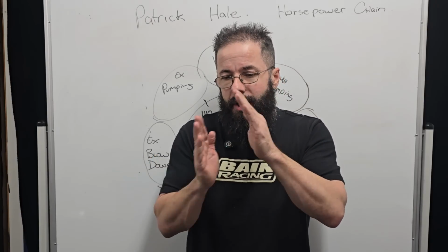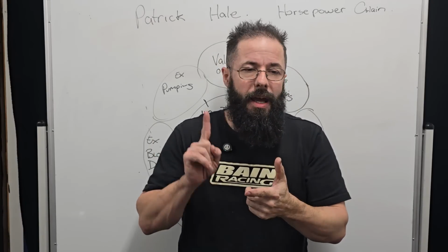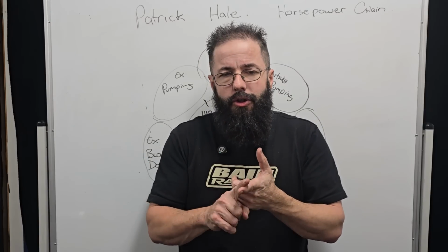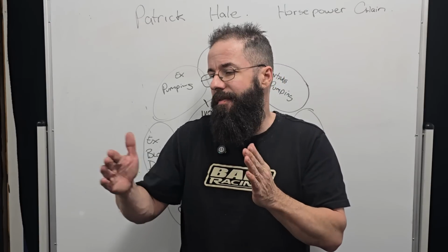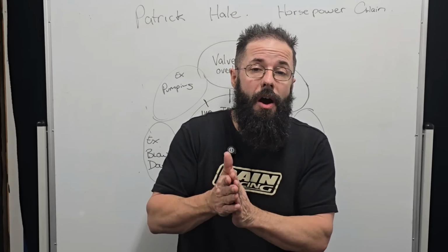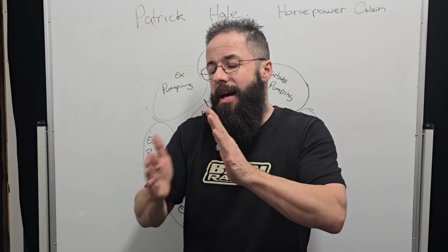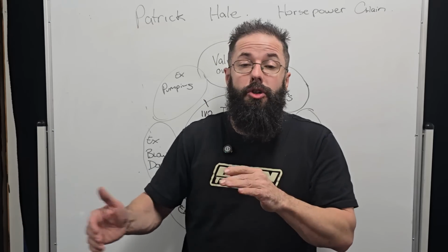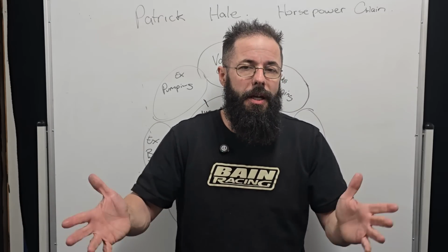But if you look at the trailing distance in that, we could have a 260 at 50, but it might have 300 or 295 or 310, and that's that trailing ramp. Yes, it's soft on valve train, but some of them are just too long, and this kills dynamic compression.